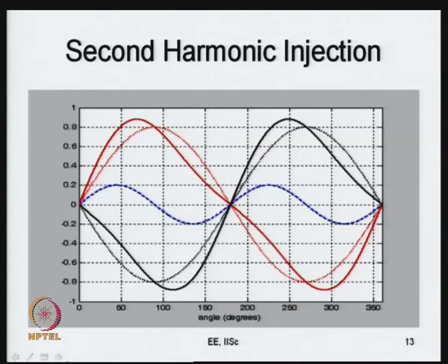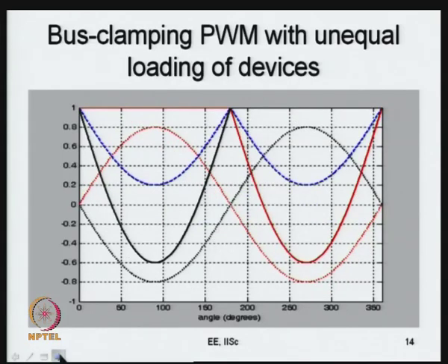Okay. So, now it is possible to add fourth harmonic like this, sixth harmonic, eighth harmonic or anything, any even harmonic really like this now. You can add that in such a fashion that any signal which is at double the frequency. Now, you see this blue signal, what is this blue signal? What is the frequency of this blue signal? Twice the modulation frequency. You see the red sinusoidal wave, if you call it 50 hertz, this blue is at 100 hertz now.